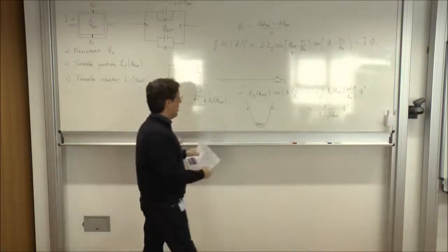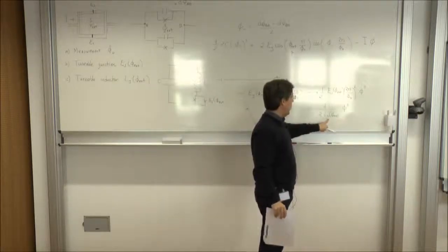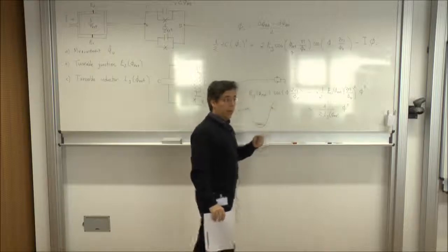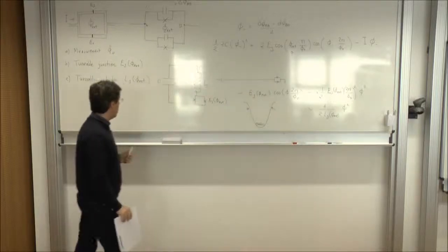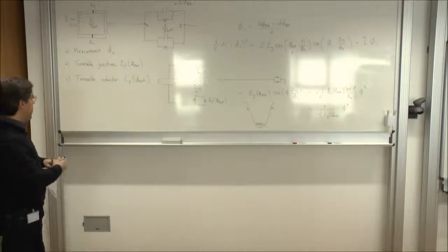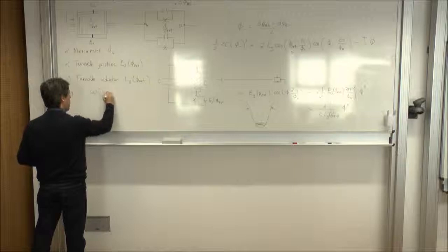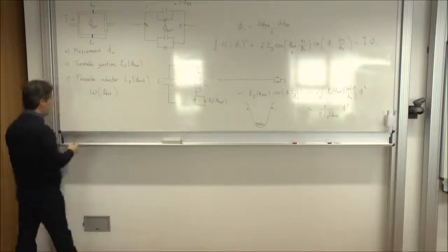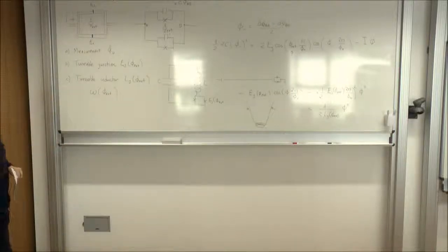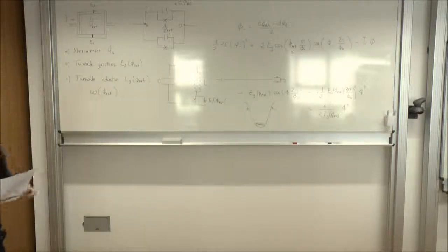The nice thing is that because our Josephson energy can be tuned, you can make this inductor tunable. And this introduces the possibility of having a resonator frequency that depends on this external flux. And that's also the basis of parametric amplification, driving oscillators. Okay?